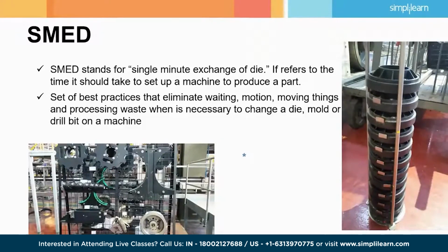Another Lean tool that is very much used is SMED, which stands for Single Minute Exchange of Dies. It refers to the time it should take to set up a machine to produce a part. It's very common, and as you can see, there are some examples of companies that need to do fast changeovers. SMED is a very good tool to reduce the time of the changeovers. In automatic plants, there are numerous instances where it would take like 3 or 4 hours to do a setup. With the use of these Lean techniques, the setup time would be reduced to minutes.